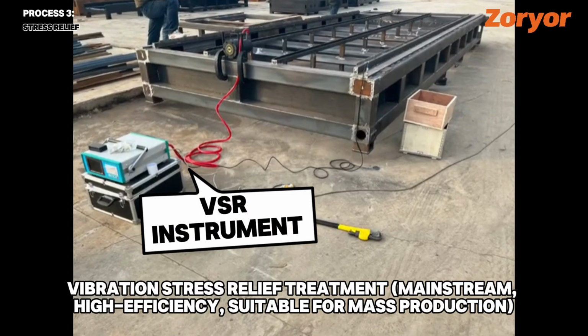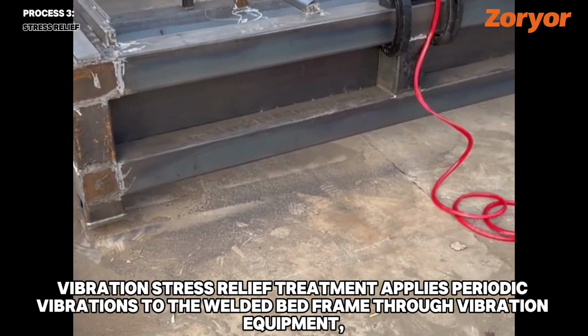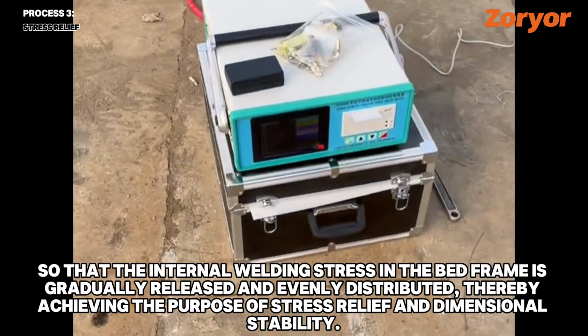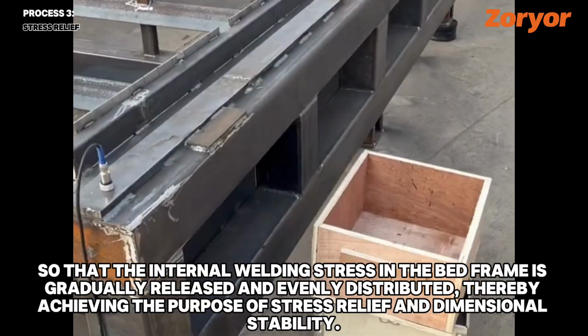Vibration stress relief treatment. Vibration stress relief treatment applies periodic vibrations to the welded bed frame through vibration equipment, so that the internal welding stress in the bed frame is gradually released and evenly distributed, thereby achieving the purpose of stress relief and dimensional stability.